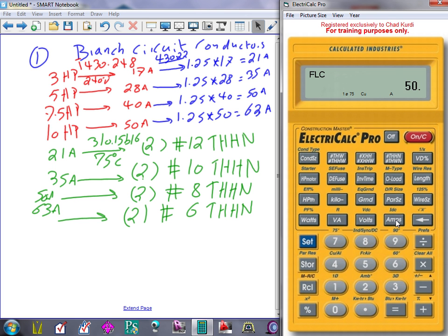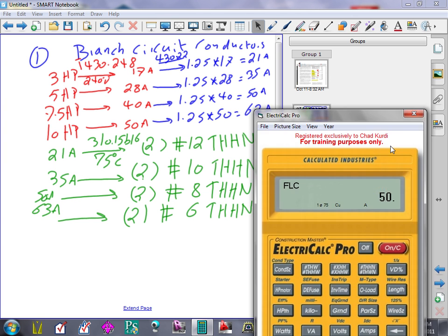Cool? Okay, so what if your conductor is in the 60s? Why do we give you the option? What if you're using TW conductor to feed motors? I could be using a TW. Then here's what you do. You set 60 and you size everything. Same process, except you change it to set 60 degree and you size everything based on 60. Cool? Done.